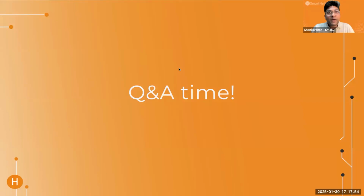To be very honest, what can be done? First you need to make sure that even the irradiance data is correct. But let's say I've figured that out. As long as I have good irradiance data, I can understand, based on the metadata, the kind of inverters and modules used, and the array configuration, what my expected value is. Then I can make some corrections to the data. At the end of the day, we need to treat the data. If the problem is at source, especially because of communication protocols or aggregation logic, it becomes more difficult. But if there is missing data, it's relatively easy to work with.